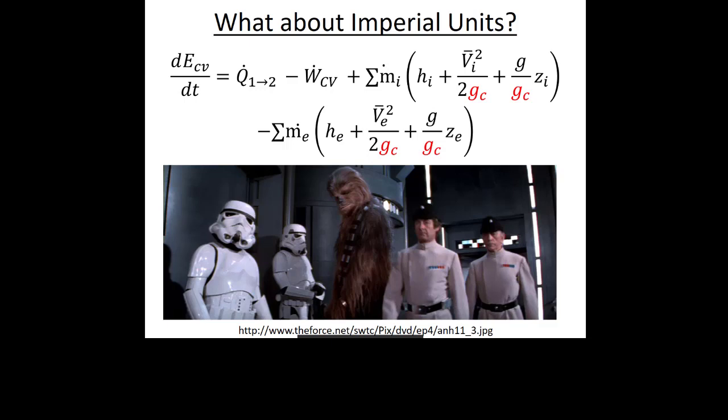And you might think that tons is a unit of mass, and it is, but it's also a unit of heat transfer rate, because it's about how much heat you have to add to melt 1 ton of ice in a given amount of time, right? So we got all these really weird units in thermodynamics, so we always want to carry our units in our math, right? So it's always going to be this kinetic and potential energy term, if they stick around, that gives us problems.